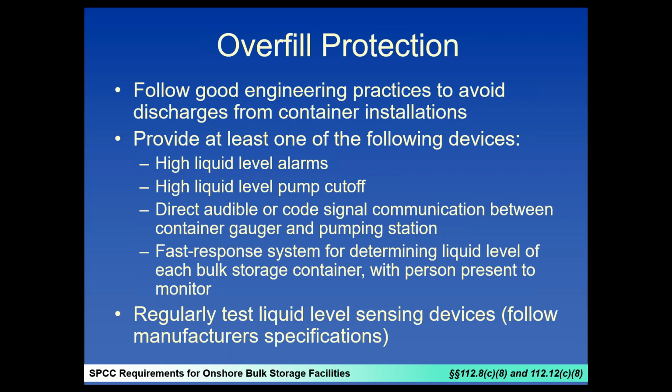You have to have that on the tank, and you don't have to have it on a drum. Anything where you're not filling it again, you don't have to have it. But for a typical tank that you're filling, you have to have overfill protection. And it's super important to test it, make sure it works.